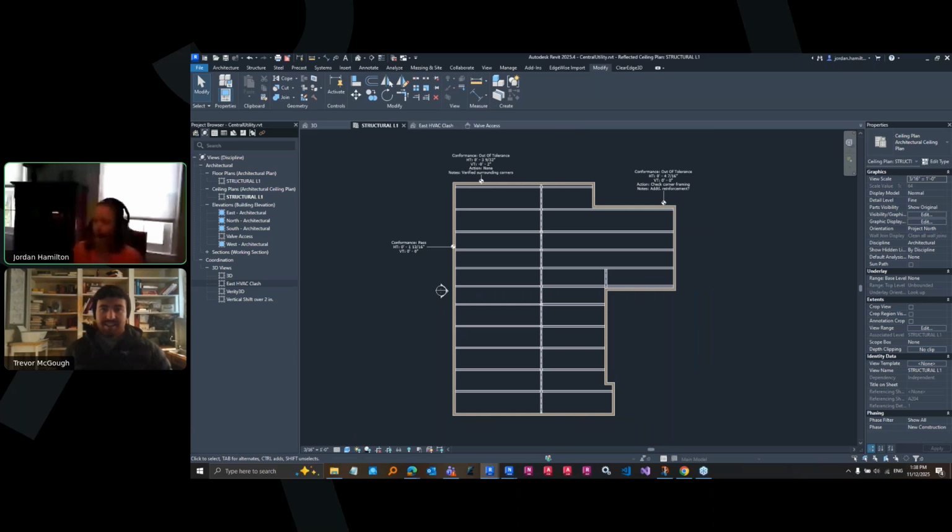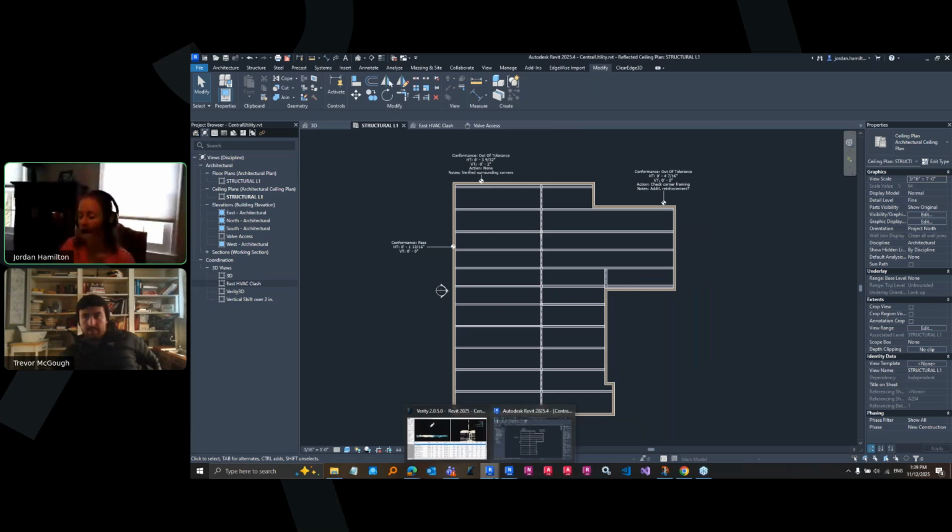Yeah, definitely. And then let's talk about the last big one as far as the host program integration here, representing the Verity as-built fit. So Verity is finding the true location of these model objects based on the point cloud, but how do we show that in the model? How do we represent that for the people that need to see it? And that's one of probably only two areas where Verity for Revit and Verity for Navisworks are different from one another.